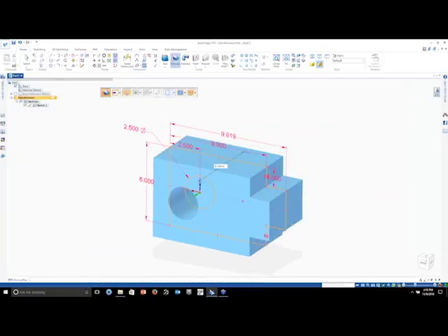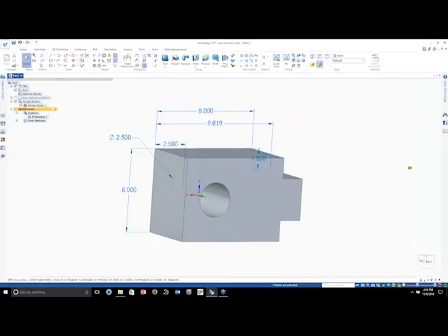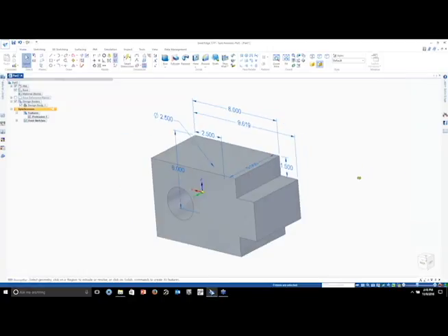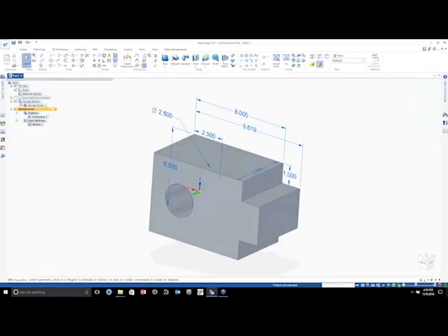In this scenario, I like to use a symmetric. I want it to go symmetric about the coordinates. So I'll click this. If I want to use a shortcut, the shortcut for you is Shift on your keyboard. So hit Shift, and that will toggle you between the symmetric and non-symmetric instead. So I'm just going to say 5, and there we have it.